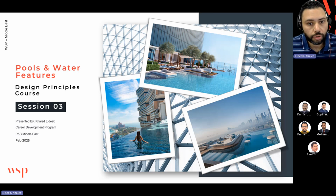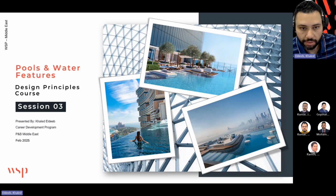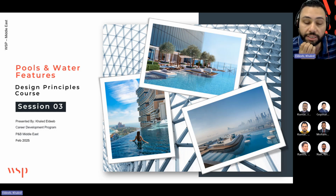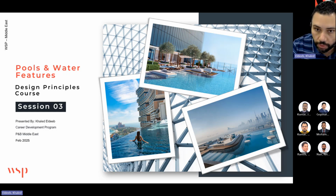Okay. So hello everyone. Welcome to session 3 of the swimming pool design course. So far we have completed 2 sessions already, and if we do a quick recap of the key points that we discussed in the last session, we spoke about how to do the hydraulic calculation, like how to size the circulation pump in terms of flow, TDH, total dynamic head, horsepower, and the kilowatt as well.